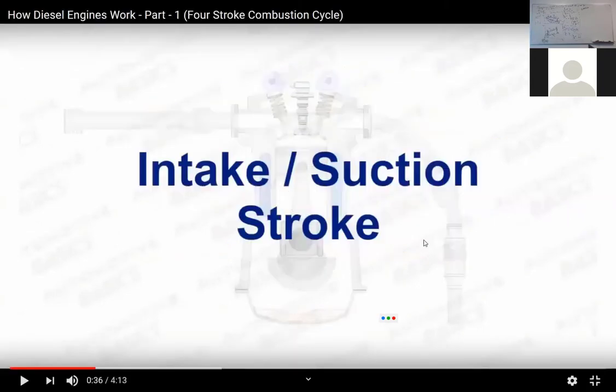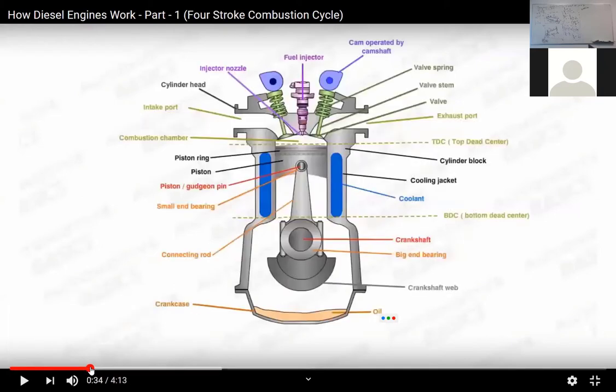So he first gives all the names of the components and parts. We care about the piston, the crankshaft, and the cylinder. This is a cylinder, this is a piston, and this is a crankshaft, which is going to spin because of this movement. This linear movement becomes rotational movement due to this design, which is called the crankshaft. We have here the intake, here the exhaust, and this is the fuel. He will now describe stage by stage what will happen when it is open.